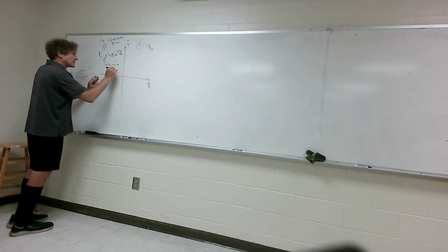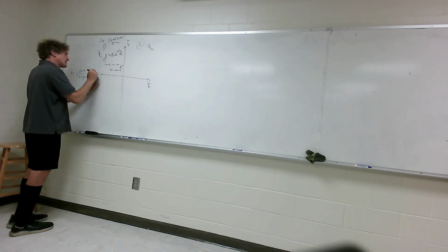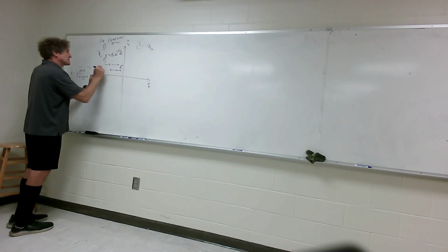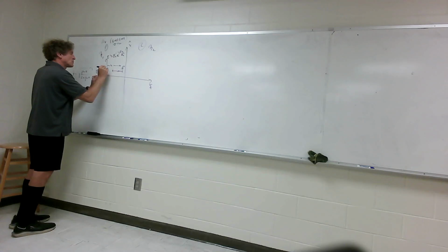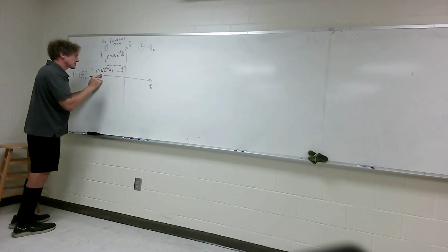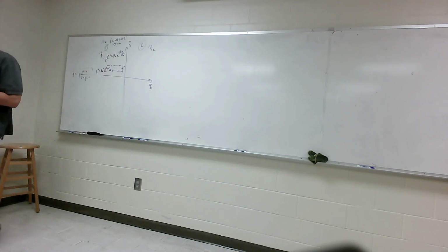There's also going to be a reflected electric field, and I'm going to say that E reflected is given by E naught reflected times e to the plus j beta 1 z a_x. Does everybody understand the plus j is necessary because it's moving in the opposite direction?